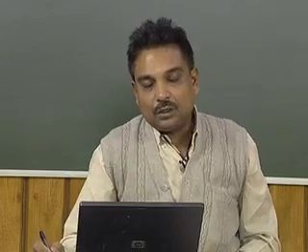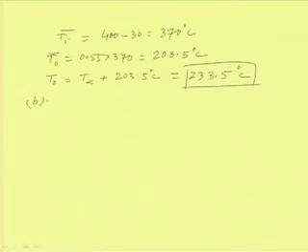Now we have to find out part B of the problem. It says we have to find out the local temperature T at a distance of 8 centimeter from the surface. That means here we have x by L. We have a chart plotting T bar versus T0 bar versus 1 by Biot number, when x by L is variable.